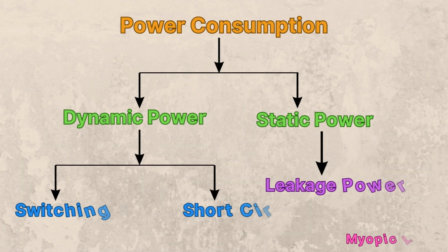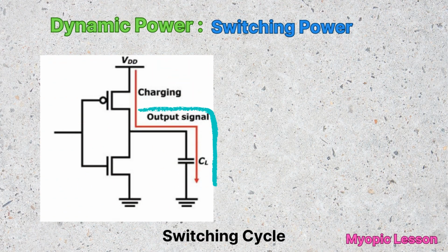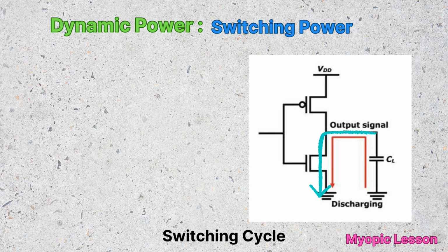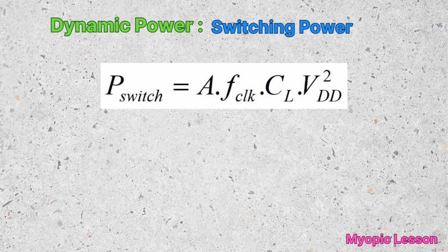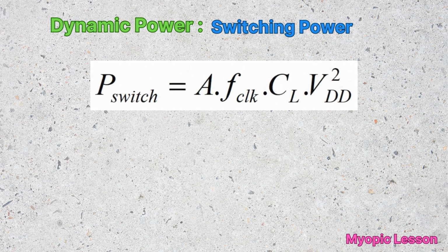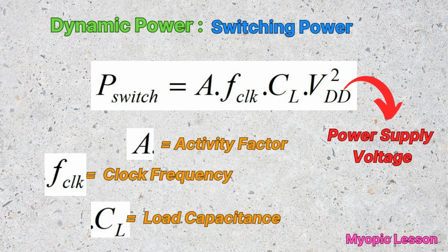Let us investigate the sources of power consumption. Obviously, it has various causes and types. Every MOSFET has a capacitive effect. The capacitors are charged and discharged in every switching cycle. The corresponding power loss depends on the clock frequency, value of load capacitance, and the number of switching taking place per cycle of clock, called activity factor. Obviously, the switching loss heavily depends on power supply voltage.